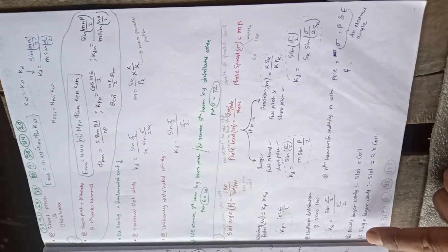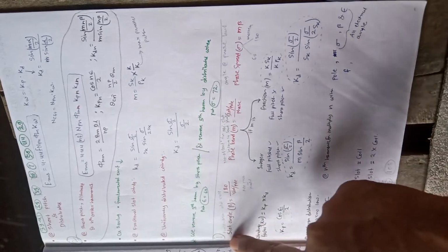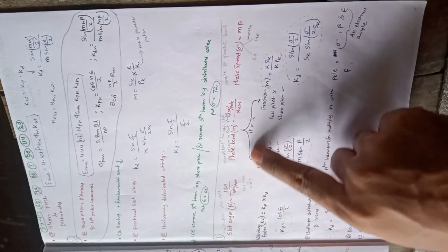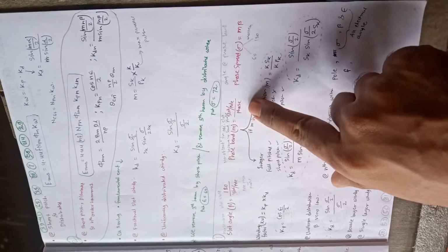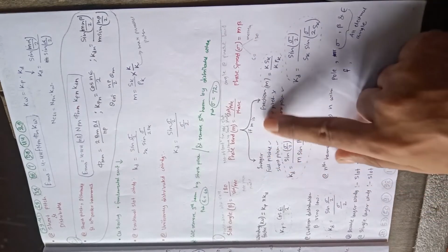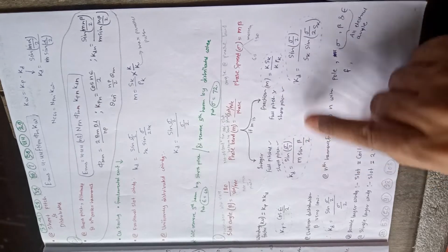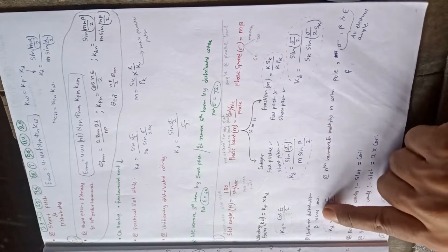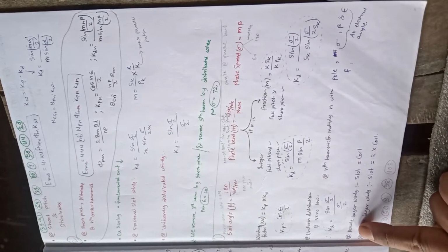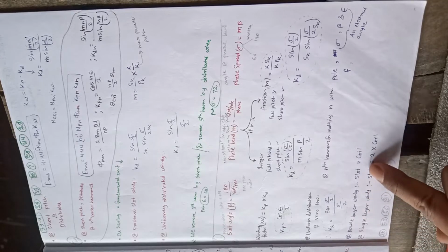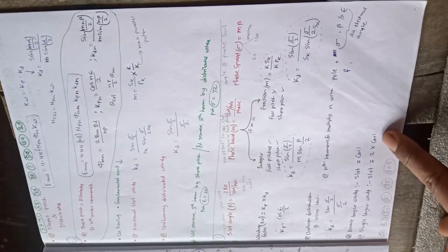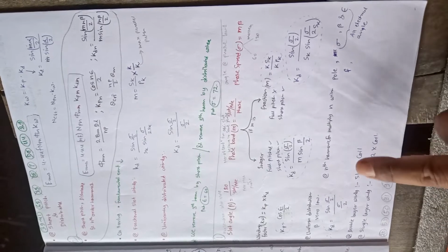Okay. And another point we have to keep in mind is slot angle beta equals 180 upon slots per pole, phase belt m equals slots per pole per phase, and phase spread sigma is m beta. Correspondingly, when m is an integer and when m is a fraction, we have the corresponding distribution factor. And the third type of distribution factor is for uniform distribution, and then kp and winding factor. Okay, these things we have to remember. And another part we have to remember is when it is double layer winding, the number of slots equals the number of coils, and when it is single layer winding, the number of slots is equal to 2 into the number of coils.